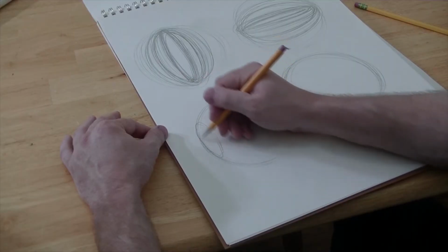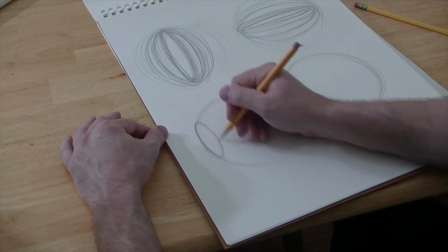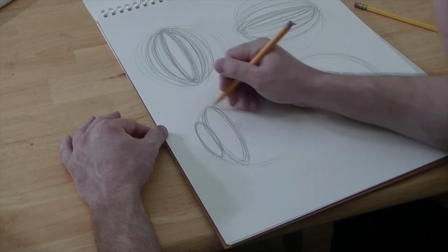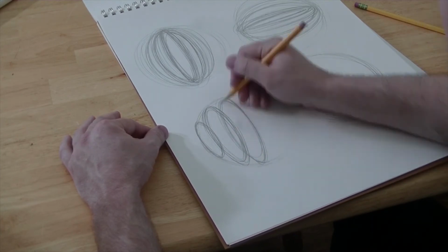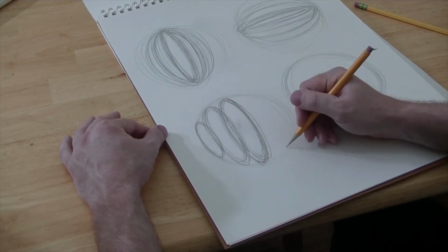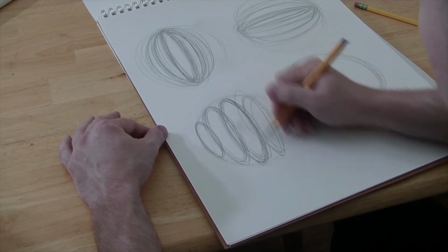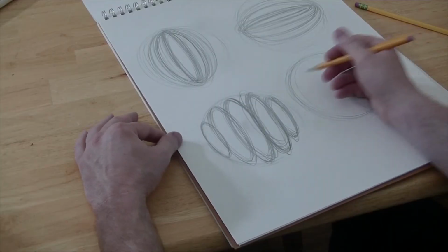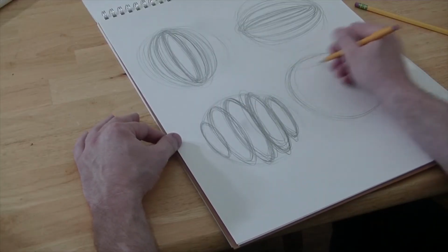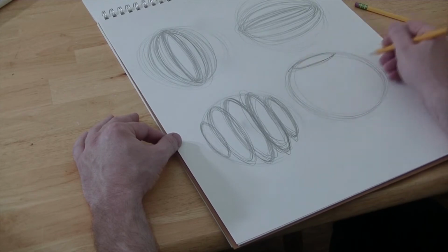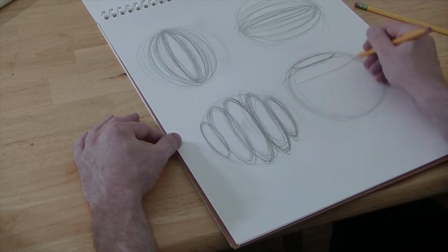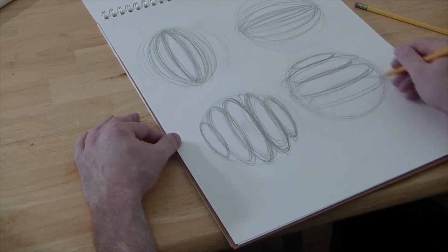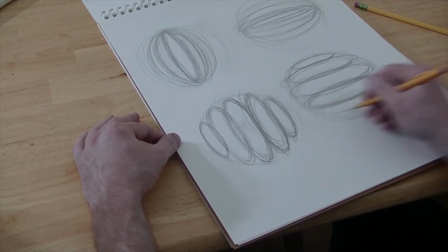Number 3. Draw a series of vertical ellipses across the circle, each touching the circumference at their top and bottom curves. They should all have the same degree of eccentricity, but change in size as they go along. Start the smallest ones on the outside of the circle, then make each one larger until the middle. Number 4. Do the same with horizontal ellipses. Use the same approach to drawing ellipses as you did with circles. Let your lines flow and correct as you go, keeping the major and minor axes in mind. Okay, start.